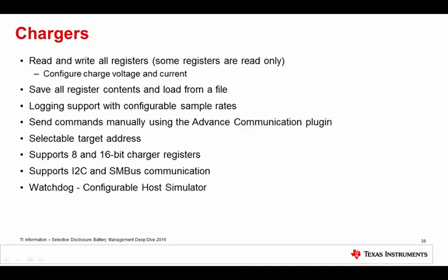Really briefly on chargers, because I focused a lot on gauges. So for chargers, again, we get to read and write all the registers through the workspace associated with the charger product line in BQ Studio. You can save all the register contents. We've added logging support recently. You can send commands manually using an advanced COM plugin. So same with gauges. If you want to use low-level COM for chargers, you can do that. Select your target address. There's 8 and 16-bit charger register support. Recently added 16-bit support for that. And again, support for I2C and SM bus on chargers.